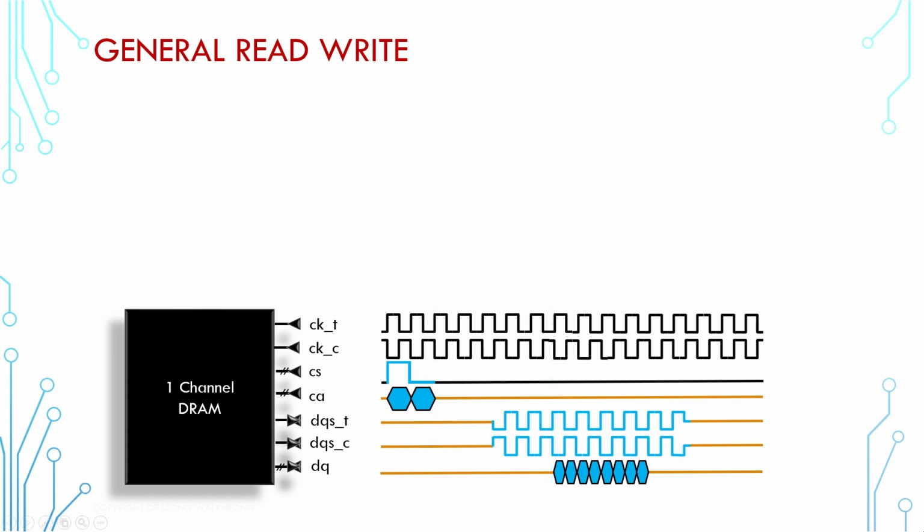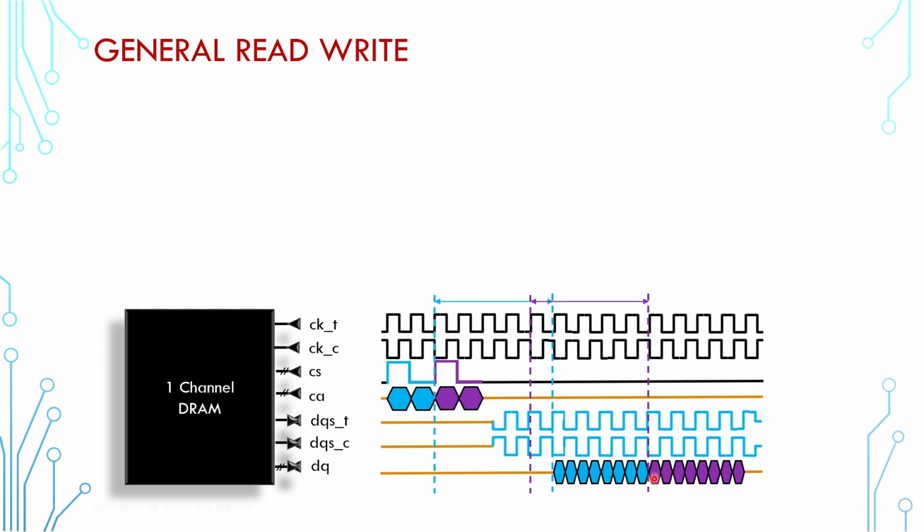And now this is possibly the most interesting and also the most challenging aspect of DDR operation. Say if you want to send two write commands, can you send it this way? You should know by now that you cannot because every command must obey the latency restriction. For the second command, we can imagine the data to start here, and if we backtrack the latency, the second command should start here, and therefore, generally, from one command to another, there is a delay requirement.